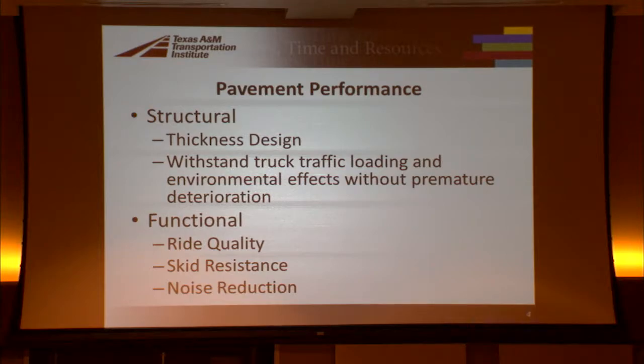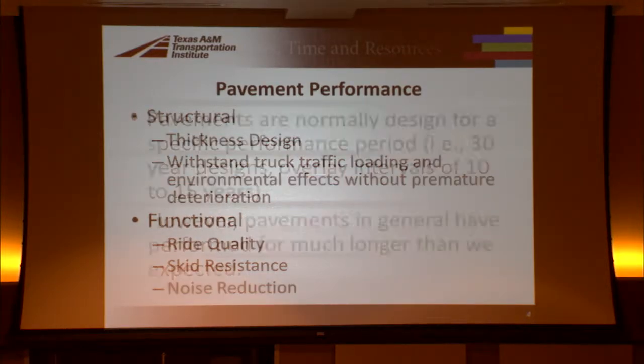In terms of pavement performance, we're looking at structural performance, and that's where we're looking at the thickness design. We're trying to have it withstand truck traffic loading and environmental effects without premature deterioration or distress. But we also have a functional component: the ride quality, the skid resistance, and also noise reduction, which is obviously important in urban areas such as Fort Worth.